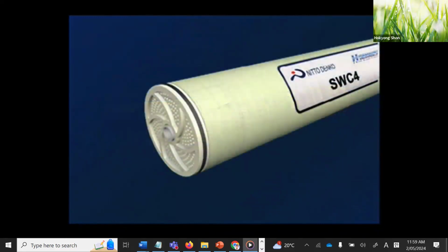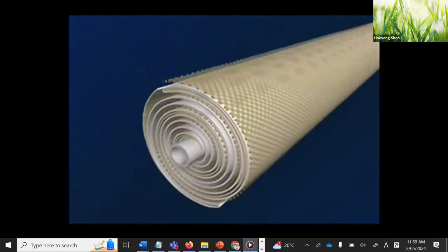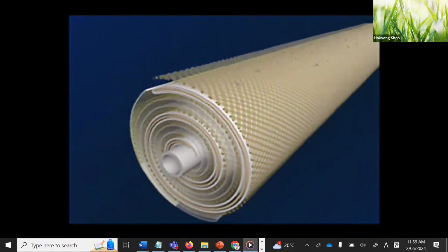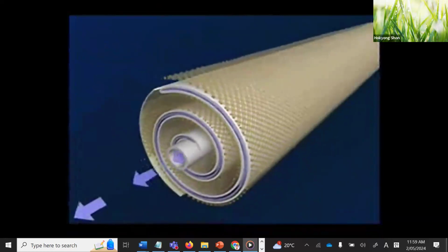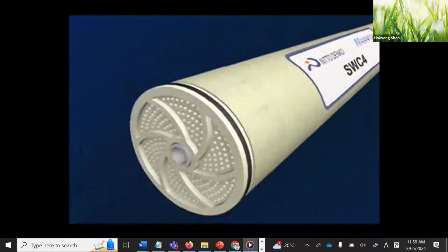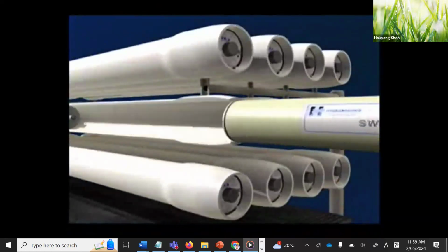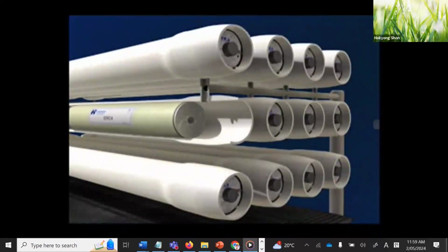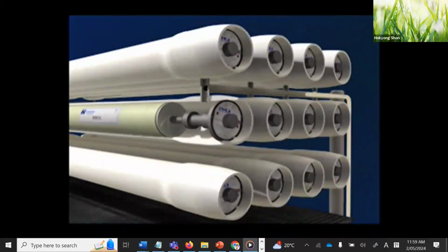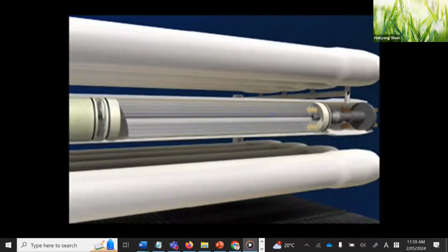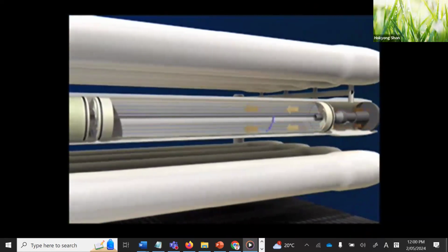With the back of the membrane completely sealed to the edges of the permeate spacer, the feed water is forced through the feed channel spacer, contacting the front or barrier layer of the membrane. Clean water, or permeate, passes through the membrane surface into the permeate channel and then flows in a spiral direction to the center of the element and is collected into the coiled tube. Hydranautics spiral wound elements can then be loaded into pressure vessels and interconnected with additional elements to complete any number of design specifications. Once the end adapter is connected to the last element and the pressure vessel is sealed, feed water can be introduced and then treated.